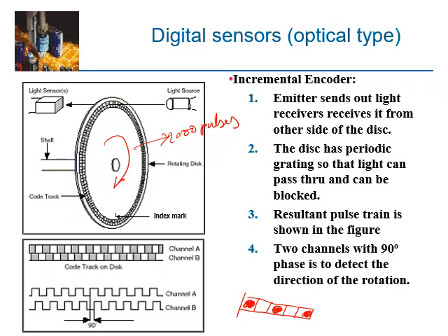So this smart technique will help you to monitor the rotation, whether clockwise or counterclockwise. But still, there is another problem, which is you are not sure. Let's say you rotate the motor and then you suddenly turn off the machine. There is no memory attached to this system that will remember the previous location of your motor.